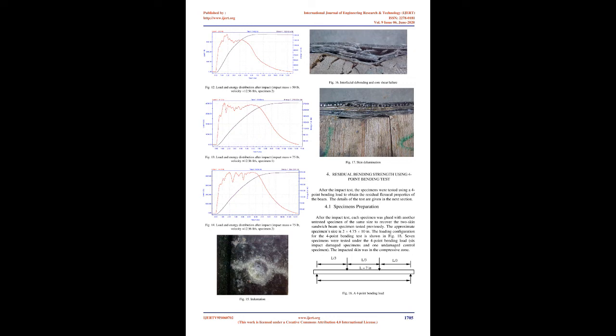For the sandwich deck, it cannot be avoided that some low-velocity impacts may occur during transportation and installation, or during paving the asphalt or concrete wearing course. Therefore, it would be beneficial to have a prior knowledge of the impact resistance and residual strength of the selected composite deck. Once this information is known, safety measures can be taken, for instance to increase the safety factor and be more cautious during construction so that a safe and reliable composite deck can serve the anticipated traffic loads.